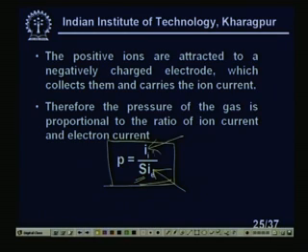So, if the pressure decreases, the ion current I_I also will decrease. If the pressure increases at that low pressure region, you cannot give some 100 psi there. As the pressure increases, this current will increase because there are more molecules, so there are more ionized gas molecules. The more ions, the more current. If the pressure falls, there are fewer molecules, fewer chances of the gas to be ionized, so the current I_I also will be less.